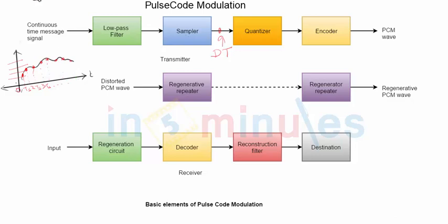For example, if the quantizer is, let's say, an n-bit quantizer, that means the number of levels in which the amplitude axis will be divided will be m equal to 2 raised to n minus 1, or it can also be m equal to 2 raised to n. That depends upon the type of quantizer we are using. For example, if n is equal to 3, then I may divide the entire amplitude axis into either 7 levels or 8 different levels. Let's say we divide the amplitude axis into 8 levels.